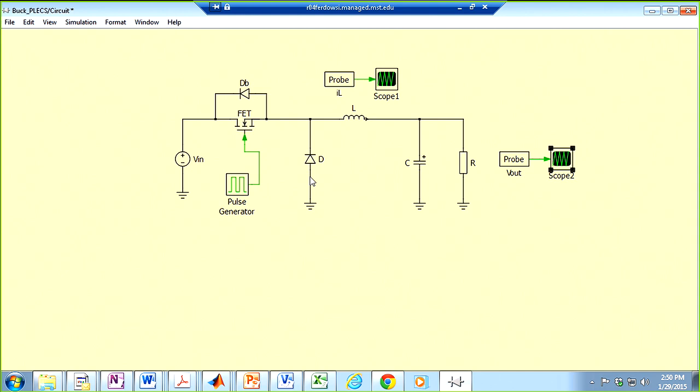For instance, there was a research group that I was a part of, and one of the students was using PSCAD, and in PSCAD, if you're measuring a signal, there's a gain of 1,000 involved. Like, you read the current is 1 ampere, in practice it's actually 1,000 amperes. And he didn't know about this. So he was running the simulation and his system was unstable, and he would say, yeah, my current is 1 amp, and I don't know why my system is unstable. Then he graduated. I mean, we never realized what was going on.